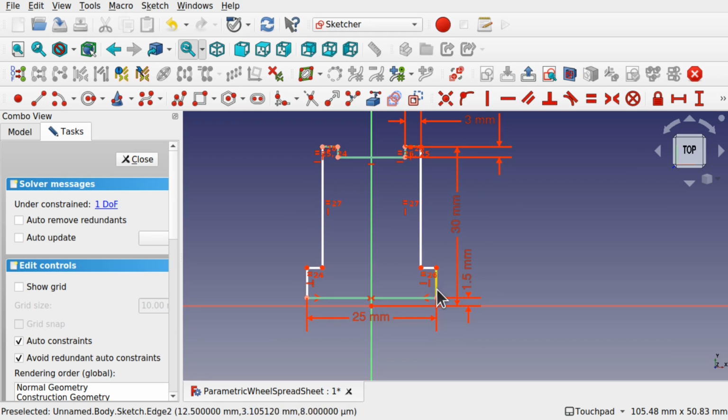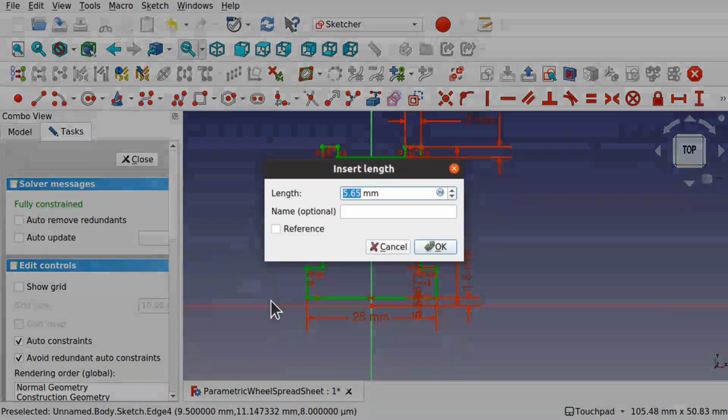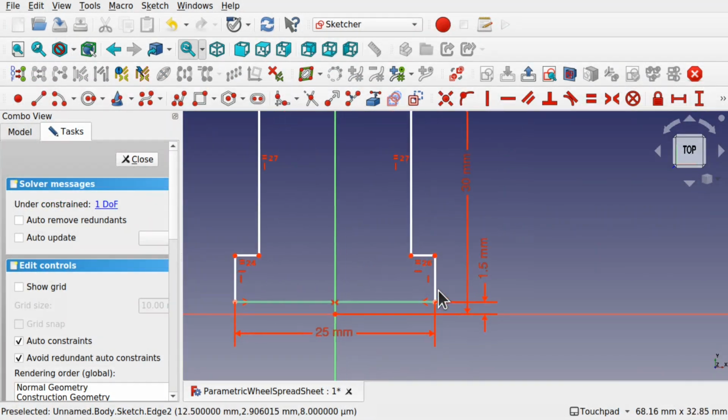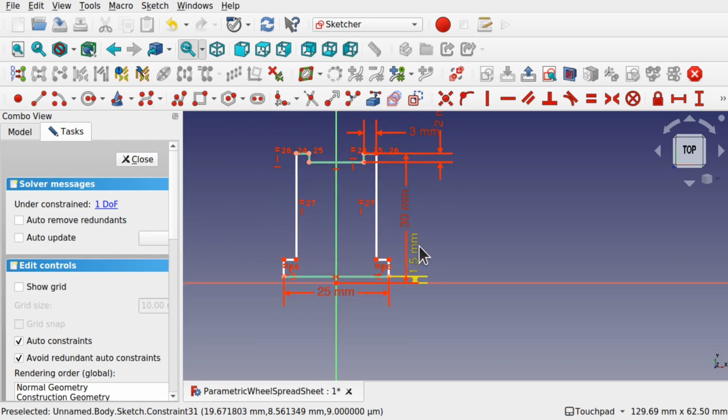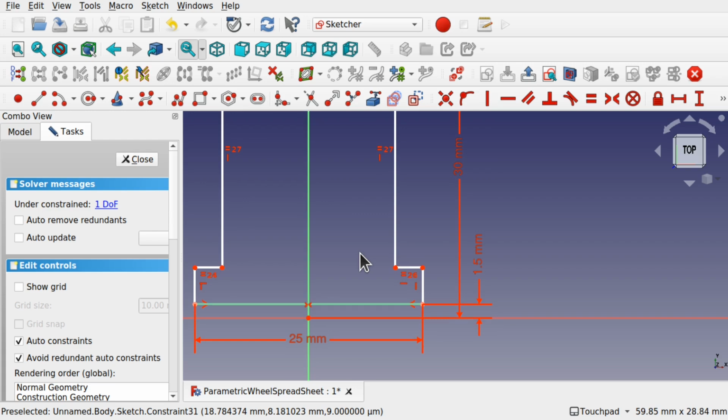There is one more length in here that we can use to fully constrain this sketch, and that's this one here. Now, this gives some strength to this hole. So if you think of the axis coming through here, then we've got this to give it some strength in here, because we're going to take out some of this spacing in here to lighten the wheel. We're going to do that later. Now, if we change this size, then this should really change as well in relation to this. So it might be something like 2% or 3% bigger than this line here.